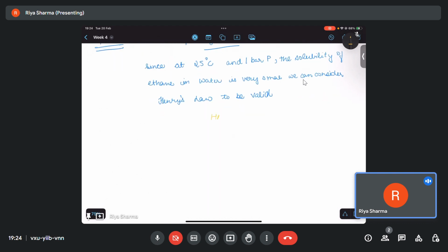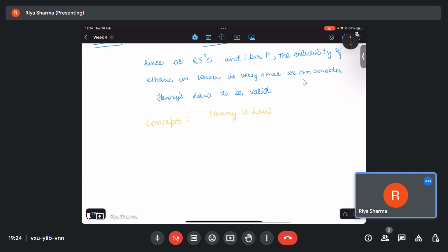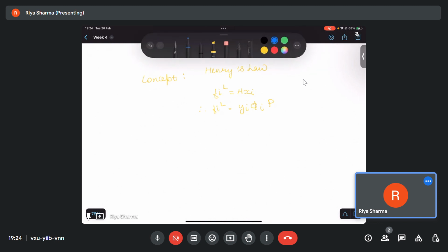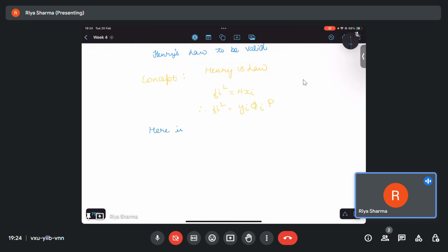And by Henry's law, what it is, fugacity of liquid fi is equal to the Henry coefficient H into Xi, therefore fi liquid is equal to Yi into P. Here i is ethane. And at 1 bar, Yi is approximately...